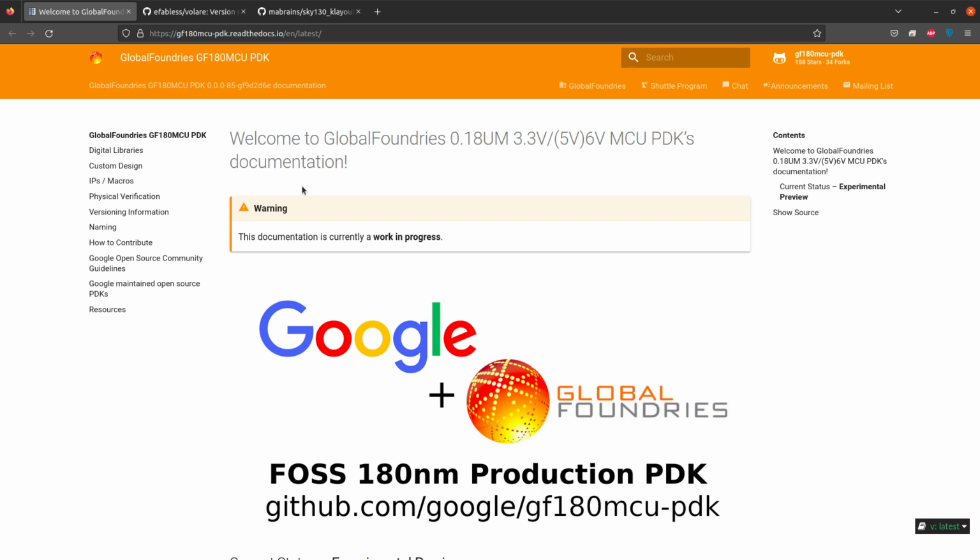We can design a full circuit from schematics to layout as the PDK contains all required files like schematic symbols, model cards, P-cell generators, verification files, standard cells, PNR information, technology definition files, and so on. Please note that this tutorial doesn't include how to install the required tools such as Xschem, ngspice, and KLayout, and we assume that they are pre-installed.